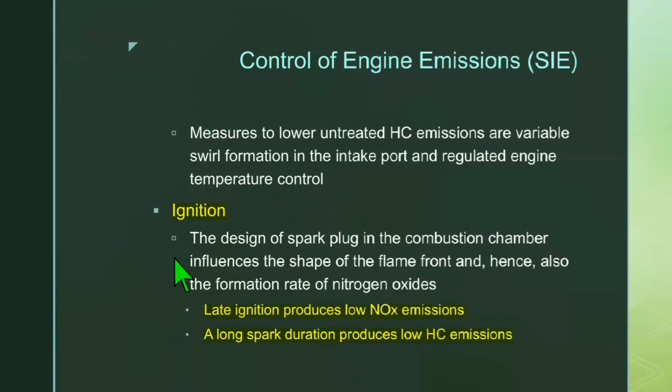Ignition. The design of a spark plug in the combustion chamber influences the shape of the flame front and hence also the formation rate of nitrogen oxides. Late ignition produces low NOx emissions. A long spark duration produces low hydrocarbon emissions.